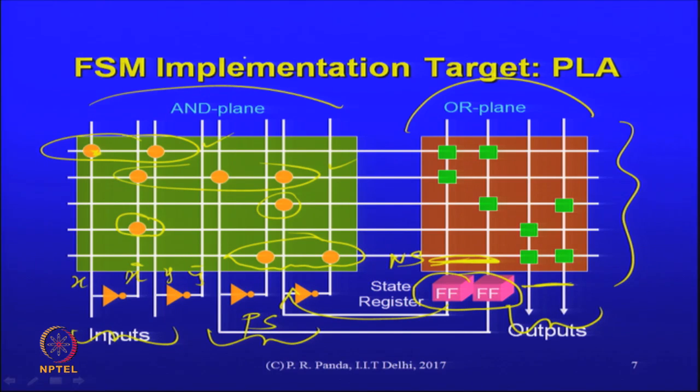Let us say initially just in the AND plane, there we have introduced a connection there, that is the programmable part of this logic. I have to decide how to program it, and programming it essentially means that I decide on those connections, which connections should be there and which ones should not be there. I introduce these two connections to mean that this line has some logic. What is that logic? So, I selected x and I selected y, the AND of those is what that line there represents.